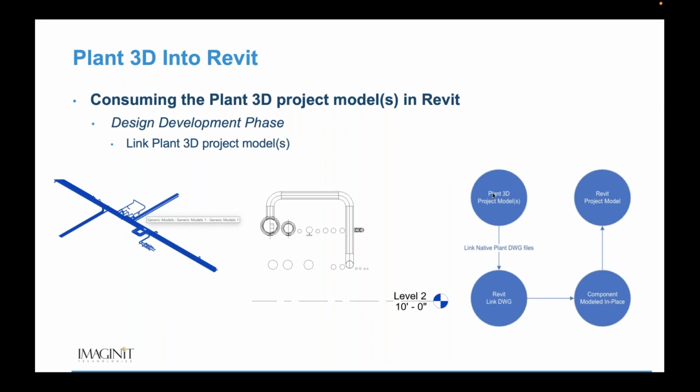I have an option of either linking the IFC into my Revit models, or I can open the IFC, which creates a new one. And again, these two methods have some different functionality. The linked IFC model basically reads the IFC data and presents it in a Revit model so that you can see that information. It's fairly clear. And if we put that link inside of an in-place family, a modeled in-place component family inside of Revit, that data will respond to view range.